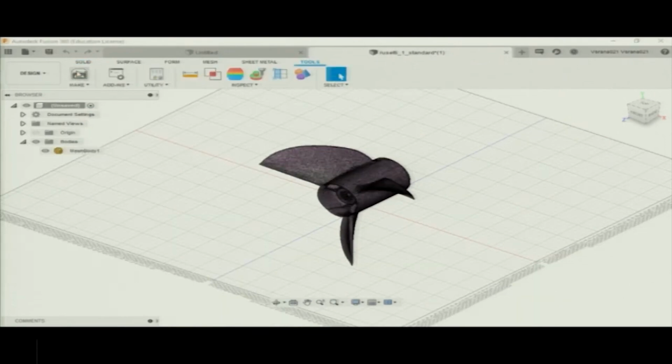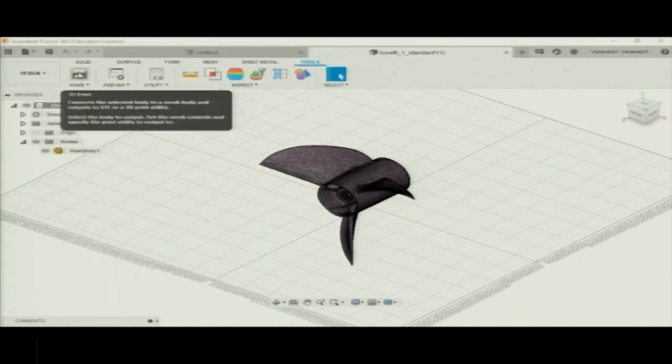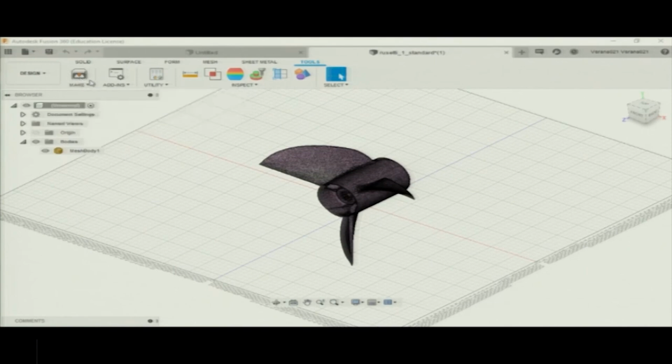Now, here is an add-on function where we have Meshmixer. Meshmixer is a tool that is used to manipulate and prepare the 3D file for actual 3D printing. So, I am working here in the tools environment. I just said that 3D printing can be used to produce almost everything, but it shouldn't be considered a magical technique that can produce anything, because it has to have supports for different components which are overhung, like a cantilever system.